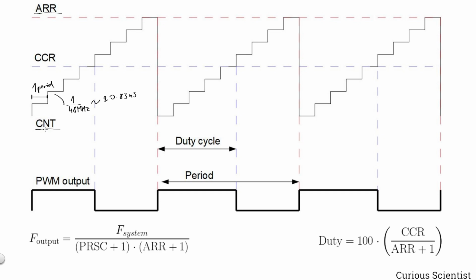And that is actually, if we look at the PWM output down here, what determines the period of the PWM signal. So basically this length, and this is one period, as it is also shown here. So that's a full period. So from count 0 to count where ARR is count, or actually the other way around, but when these become true, then that is the period.